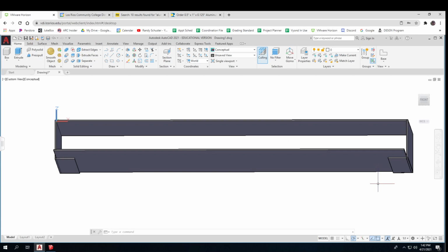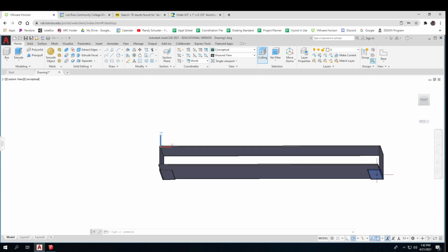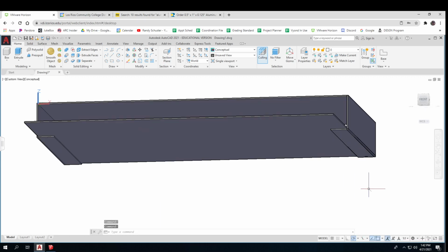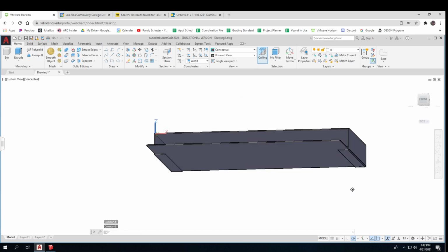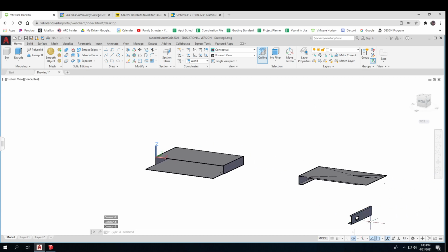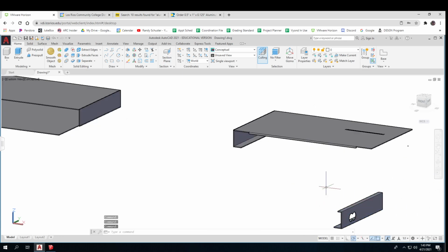It is possible to do these bends. Drill some holes and put a piece on. So that's one way. Or not drill holes and weld it. Or make it out of multiple pieces that I've done interesting things to and bolt it or weld it.